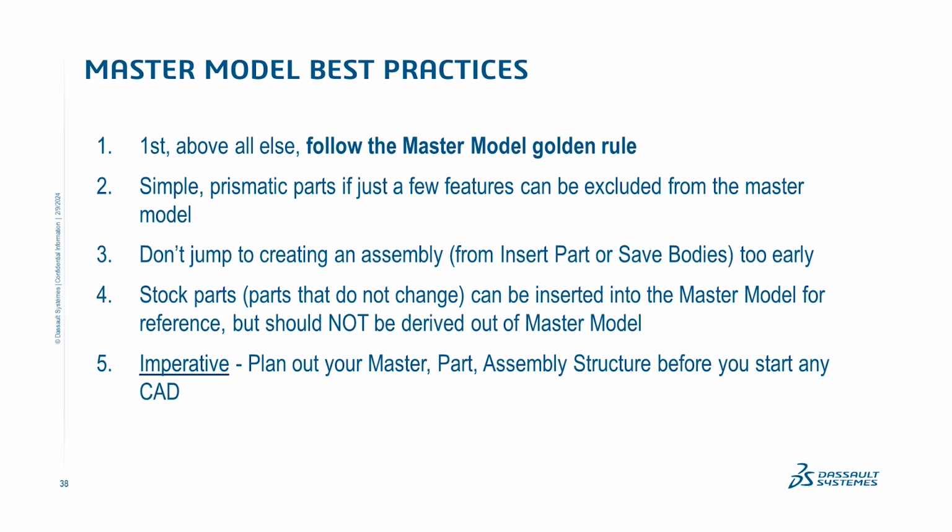Also, as you're creating your master part or master model, don't jump too quickly to building your assembly. Try to get most of your design intent into your design, and then at a certain point you're going to find that, well, I've pretty much defined this, so now it's time to derive it out using insert or save bodies.